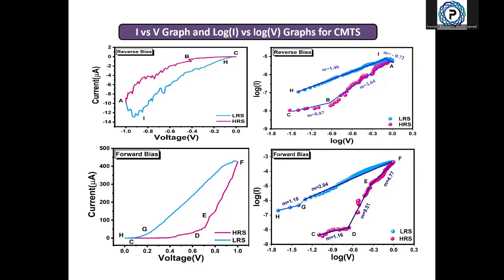Ma'am, when we increase the voltage, the electrode also injects some carriers. Suppose we have a silver electrode. When we give enough voltage, some silver atoms may lose electrons, get ionized and come into the material. Now what happens if there are a lot of traps? The silver atoms get trapped in the grain boundaries, mainly the trap centers.